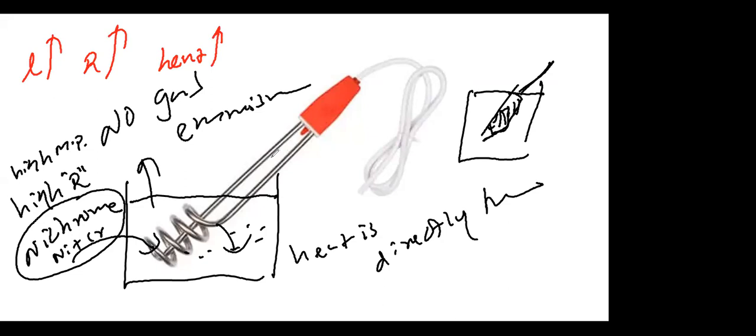Right? If between the plug point and your electric kettle or whatever there were a 1 kilometer length of wire, then what happens? The coil or wire can get overheated, and that can cause an electrical fire. Therefore here it's good, we need heat. But inside this cable it is copper, Cu, and here it is nichrome.